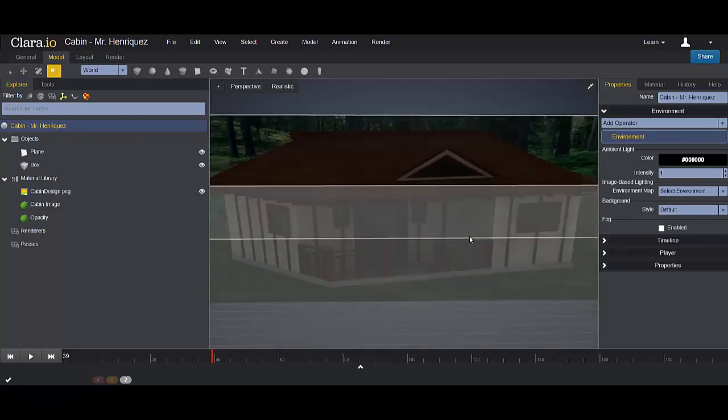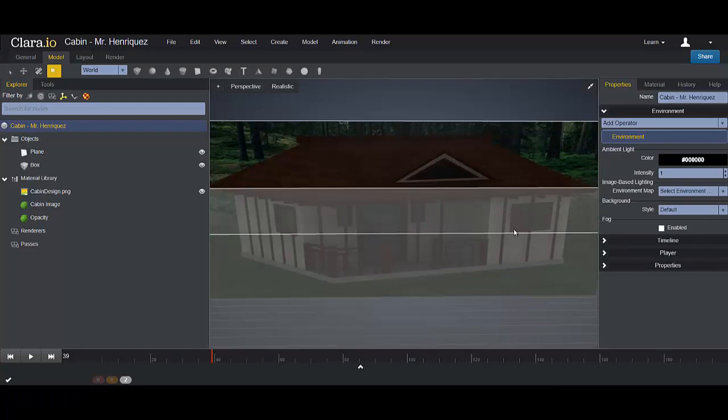This studs here or post, you will need 2 lines for those, and for the windows you'll need 2 lines. So there's 1 here, 2, 3, 4, and let's say 5, 6 for the door, 7. But again, the posts or the studs, you can do them individually after. Just add rectangles and place them against the walls.